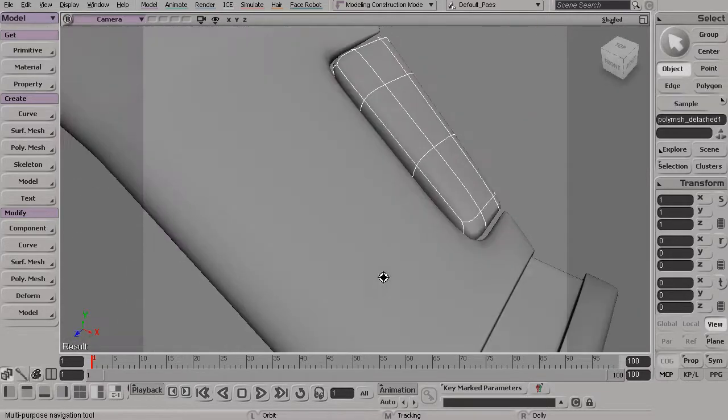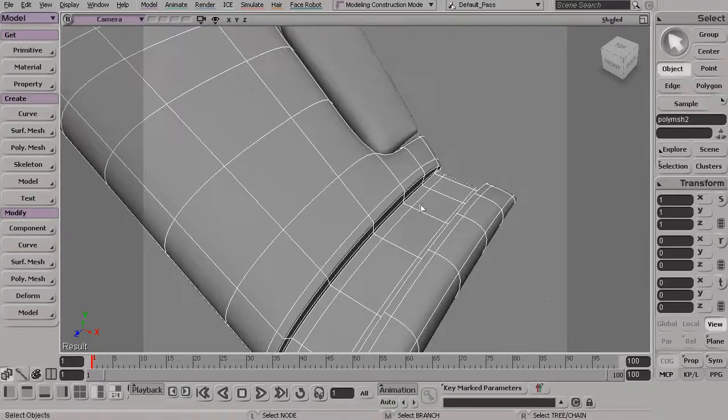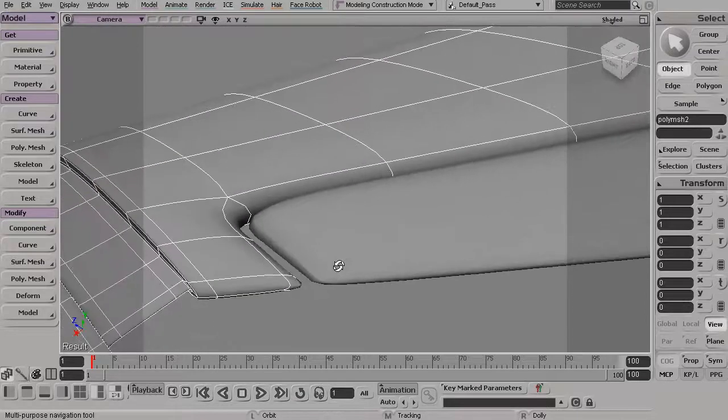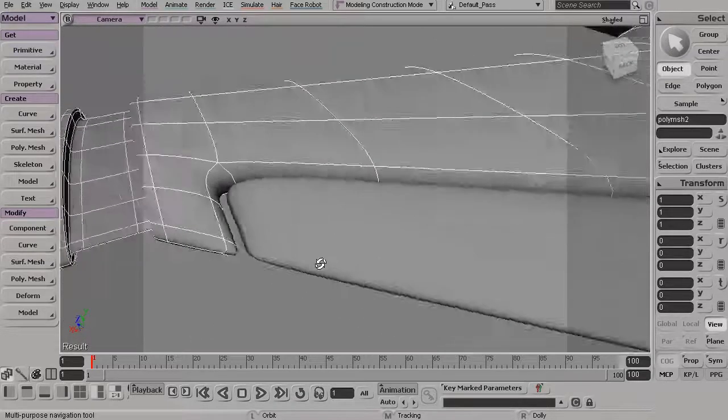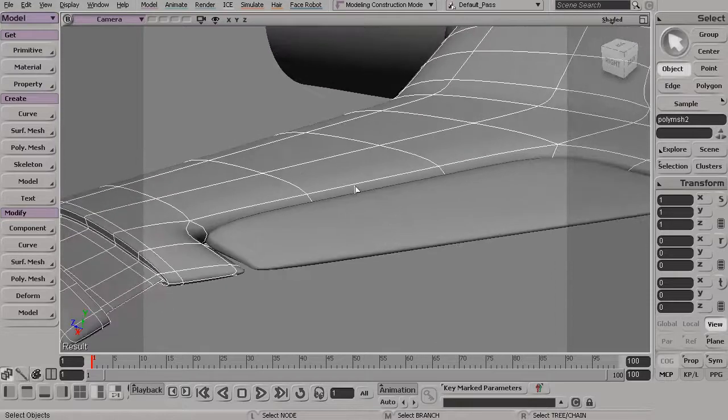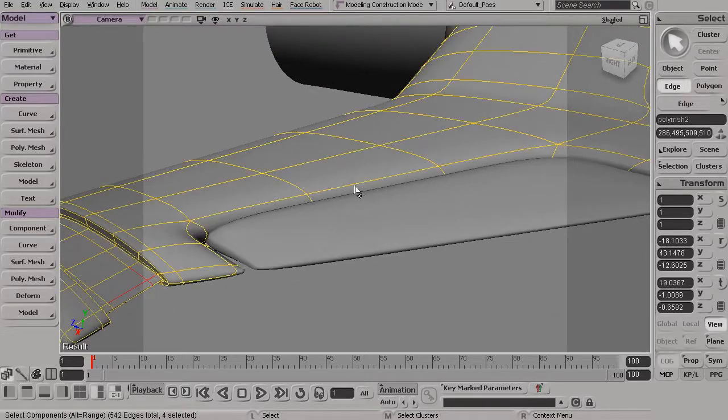Now, because of the actual shape of this geometry, it's going to become very difficult to come in here and start to add splits without just completely ruining the shape of this wing. So sometimes we can use another approach, which is the actual edge weighting feature. So to illustrate this, if I were to come into my edge selection, just press the I key on my keyboard to go to my raycast edge selection.